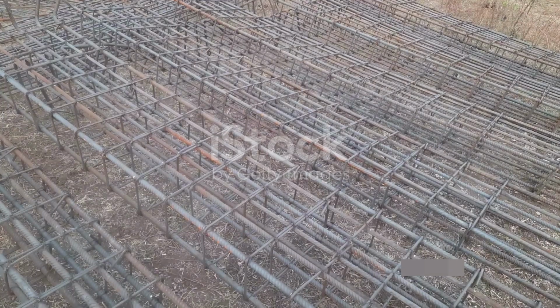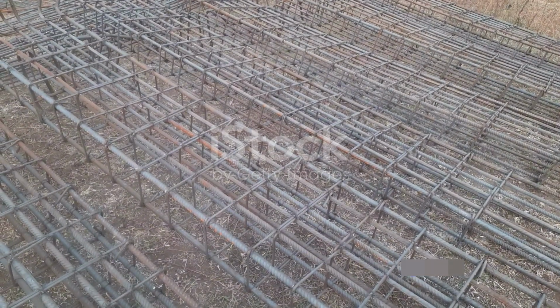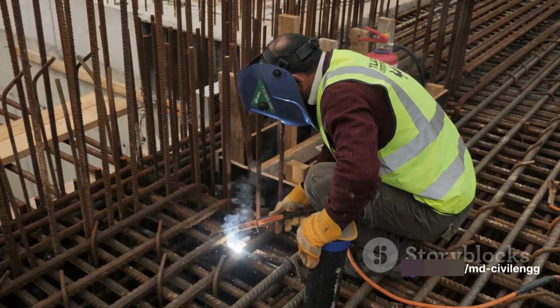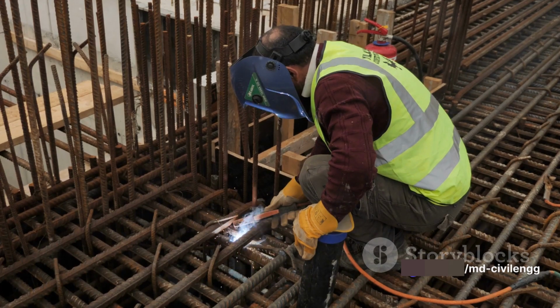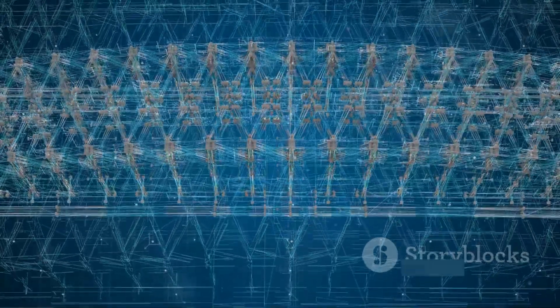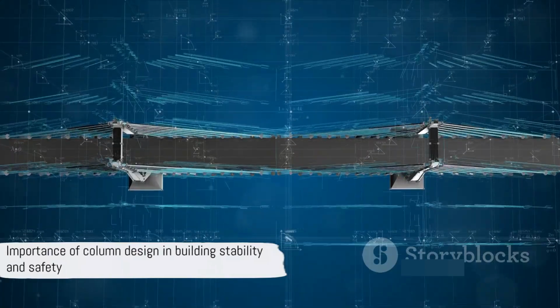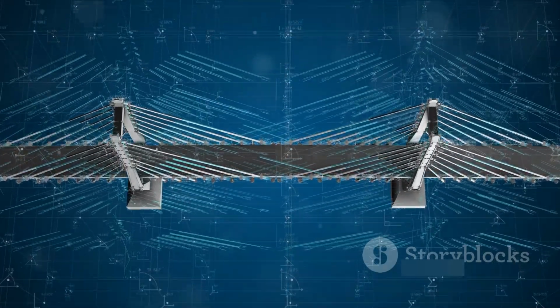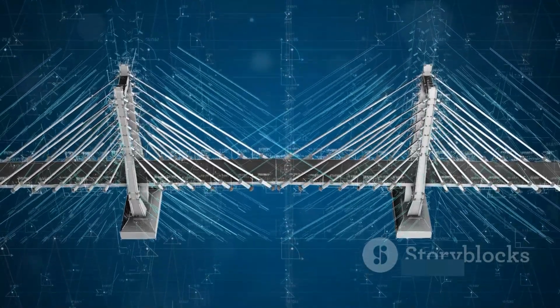We've discussed the requirements for longitudinal and transverse reinforcements, including the minimum and maximum areas of steel, the minimum number of bars needed for reinforcement, and the specific dimensions for bars and distances between them. And we've touched on the importance of pedestals and the specifics of transverse reinforcement and helical reinforcement, and that's a wrap on column design. Remember, every column in a building plays a crucial role, and understanding their design can help ensure the stability and safety of the structure.